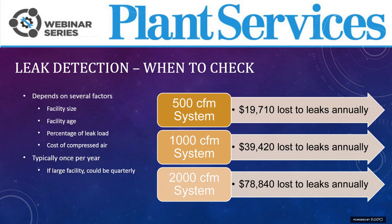If during that one check, the leak load percentage is found to be over the expectations, say significant, maybe 30%, then it would be recommended to repair the largest leaks immediately and perhaps check the leak load again in a few months. If the facility is large, then it might be beneficial to perform a leak audit once per quarter. Additionally, the cost of compressed air is going to differ from location to location. However, again, with larger facilities, the cost of compressed air can skyrocket. Therefore, a quarterly leak audit might really be worthwhile.